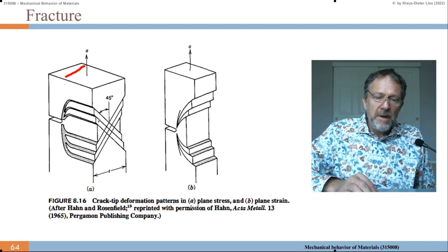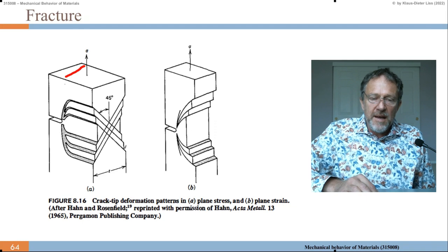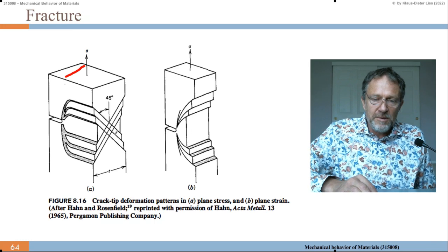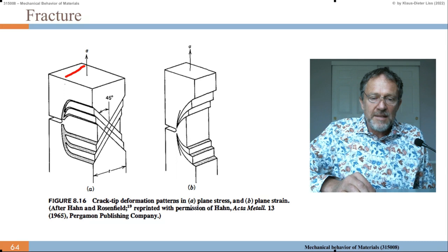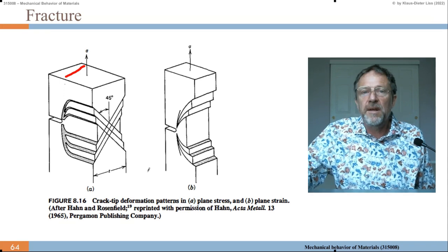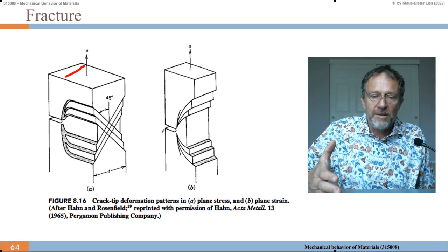So we find a lot of small crystal planes that have a good Schmid factor there, and that gives the so-called shear band, and we get slip along this direction and here along the other direction. If you put that together, if it cracks, eventually we may get a lip at one of the edges, either to the top or to the bottom. It depends which one initiates first. It's a crack nucleation and then growth process, so there are always some statistics inside.